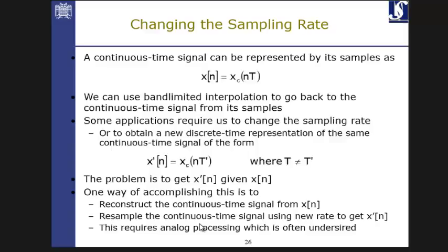It looks so crazy. Why should we do downsampling and lose some information? Or why, if we can represent a signal like this, should we add some zeros in between? But you get the concept, and when you have some practical experiment, you see that using this up and down sampling, you can reduce the amount of computational effort in the filter bank on a large scale.